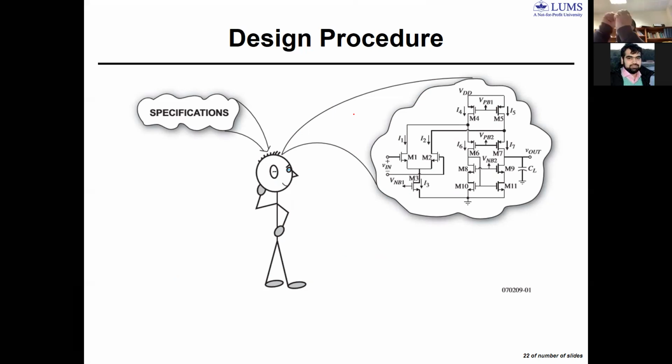There are foundries, you can send your design to a foundry so that your chip gets developed and comes back to you. Okay, that's complete. So there are three main companies. One is Cadence, they are both analog, digital and mixed signal and verification. The other is Synopsys and the third is Mentor Graphics, currently now acquired by Siemens. Okay, three companies. Mentor Graphics or Siemens is more for verification, they are not for design. Cadence and Synopsys are both for design, both analog and digital. Okay, so we have access to the complete Cadence tool.